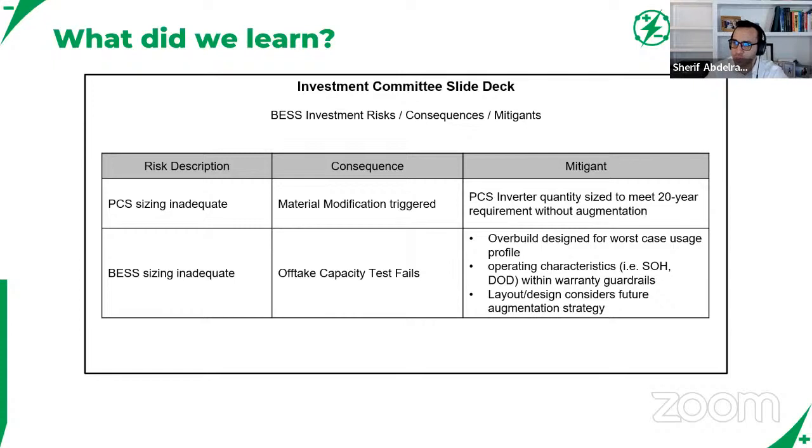But all right, I'll shift to another question by Iman. Which of these two strategies is more appropriate? Charge discharge battery from 30 to 70% state of charge for 100 times, or charge discharge battery from 10 to 90% state of charge for 50 times. And like what Iman did there, if you do the calculation, I think you'll get probably the same number of equivalent cycles, which is exactly what we did in the first optimization.